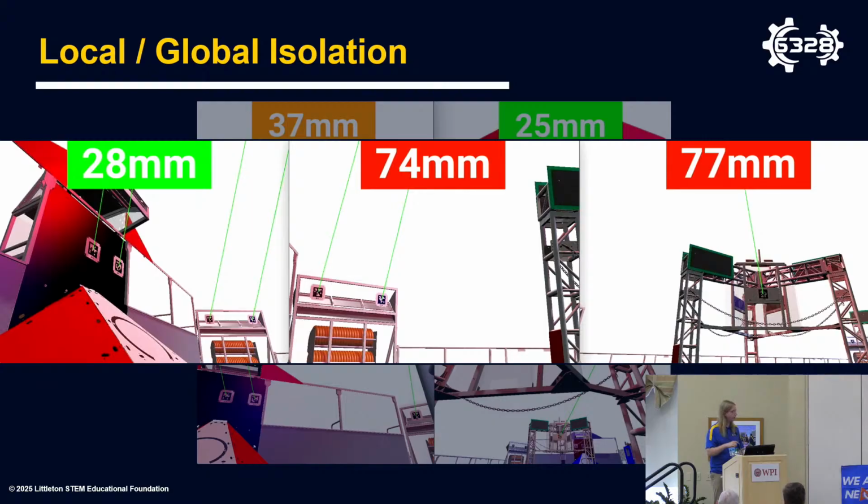I also want to note that in all of those cases, when we're shifting between different pose estimates, we're always using the same coordinate system. We're always using this field coordinate system. The difference is that it's changing so that our robot pose is correct relative to different theoretical field elements. So we can measure relative to the theoretical location of the AMP and know that we're correct relative to the AMP in reality. Now, this is something we did really successfully in 2023. This worked great, given the positioning of cameras and April tags.